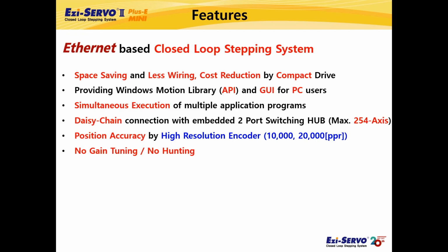In general, when controlling a stepping motor, motor heat is a problem because the maximum current flows regardless of the load. But since Ezi-SERVO controls the current according to the load like a servo, it can relatively suppress heat generation compared to the conventional stepping motors. We have looked at the features of Ezi-SERVO 2 Plus-E Mini until now.